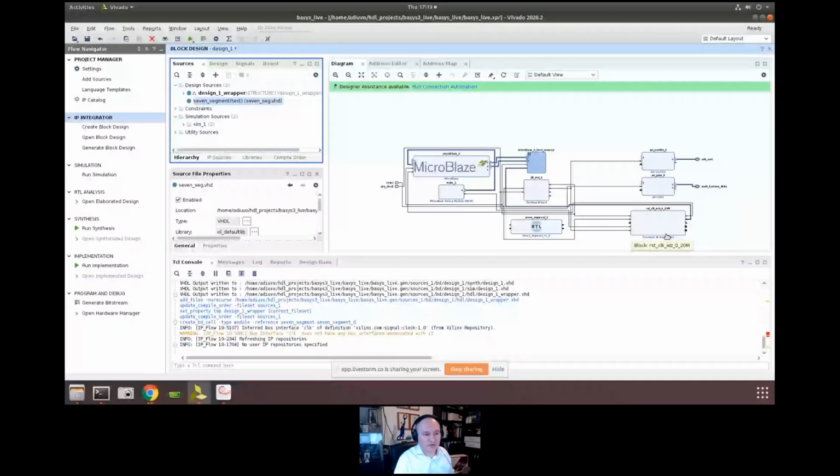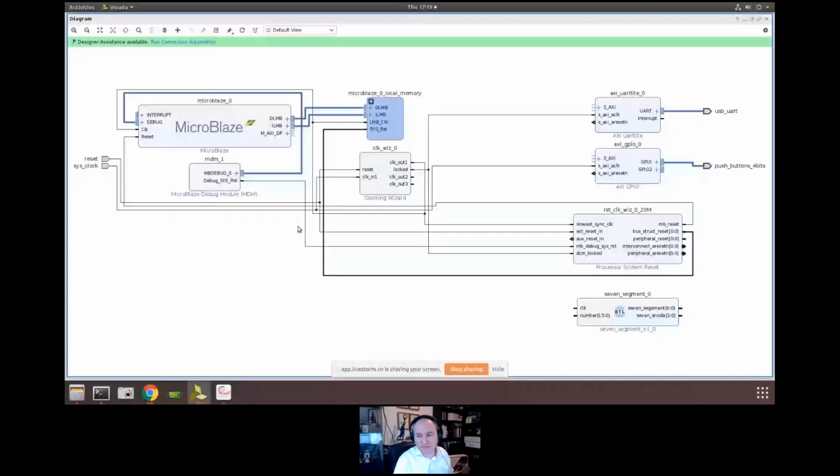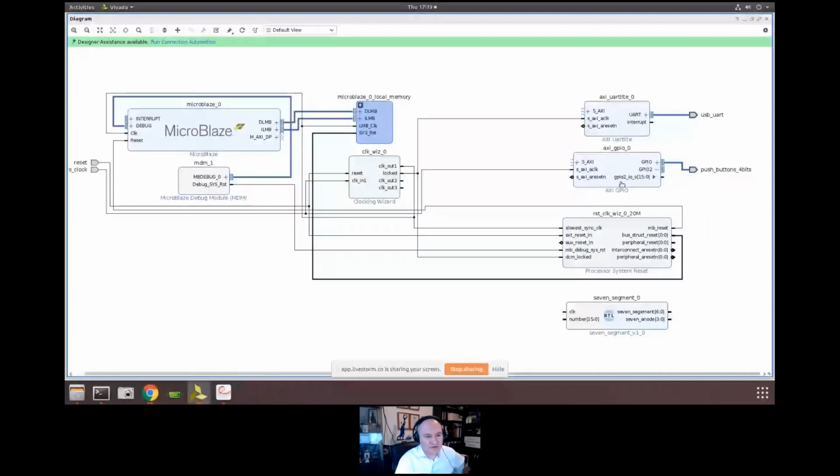Once we've got that, we're going to pull that across a little bit there. In fact, I'm just going to pop this window out so we can see it a little bit better as I work on it at a higher level. So once we've got this, we want to connect the output from the GPIO here, the one on output 2 that we've just created, to the 15 input.